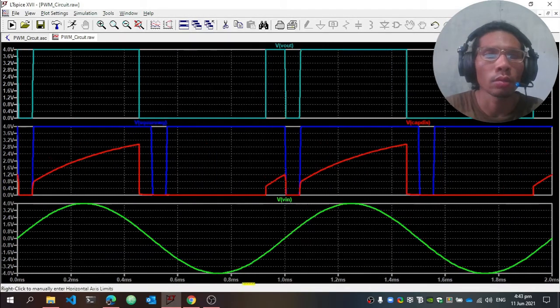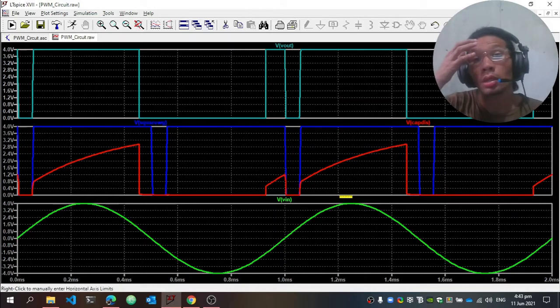Zoom in and you see a larger pulse width, which has a larger duty cycle, and a small positive high pulse with a lower duty cycle that corresponds to the capacitor discharge for the small width and the larger width capacitor discharge on the diode side.